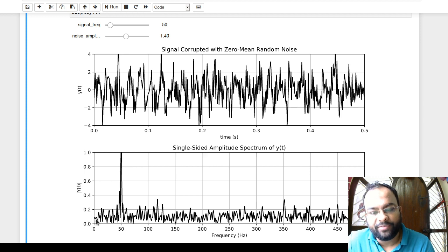While before we had 0 everywhere for other frequencies, and only a peak at 50 Hz, now we have non-zero values everywhere, which tells me that I have introduced many different composing signals here, with different amplitudes. But the important thing to note is that out of everything, one peak is very prominent, and that is at 50 Hz.